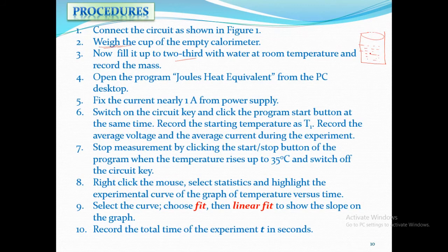Why do we fill it 2/3? Just for safety, because you have a heating element inside. If the heating element is above the water surface, not dipped into the water, once you turn it on, it will burn out, like the geyser at your home. If it is running without water, it will burn out. Similarly, you have a stirrer and a thermometer inside. All should be in the water.